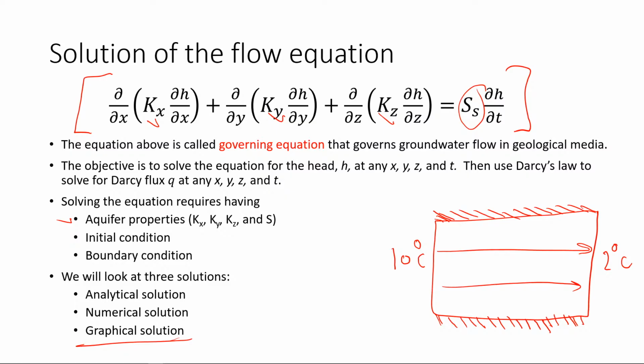In order to do this, you need to build squares here. This should be squares. So maybe that would be 8 degrees Celsius, that would be 6, and that would be 4 degrees Celsius. And that makes sense, because the temperature at this boundary is 2 and the temperature at this boundary is 10. This means the highest temperature would be here and the lowest temperature here, and you will see this temperature gradient developing. The temperature on this side would be hotter, and on this side colder.